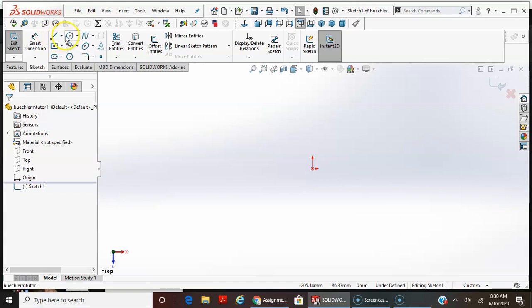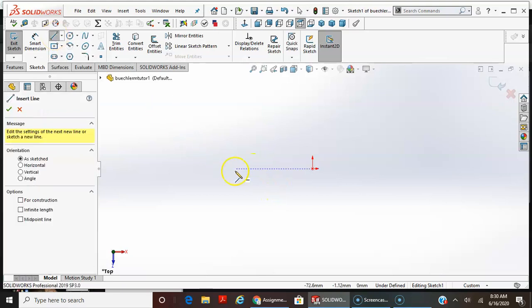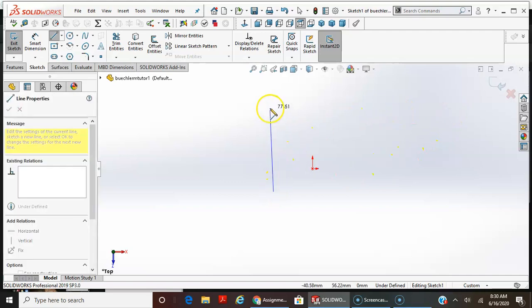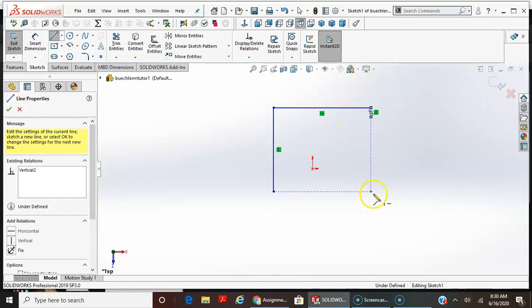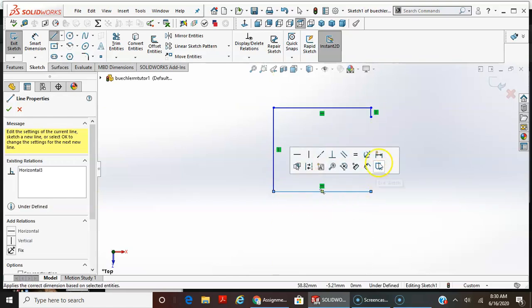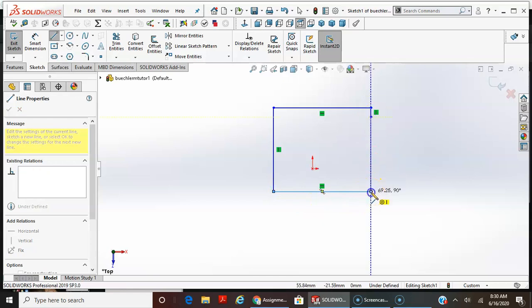And I'm going to use the line function. There's a few different functions you can use. But with the line function, if I select this in sketch mode, a pencil comes up, and I can just do here to here, to here, and I'll go back. Even though this is two lines, it still shows as a closed contour, so it shows in a shaded area.